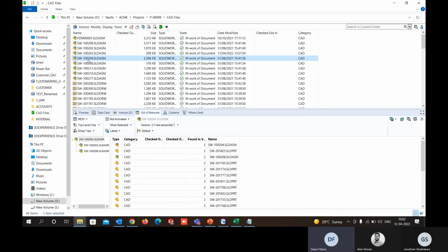The person who has to build something will pull a day's work, let's say if you get production orders for a full day. By pulling the jobs, he will get the DXFs. Those DXFs will be structured by thickness, and then he will nest those parts as per the thickness required, create cutting files, and send them to production.